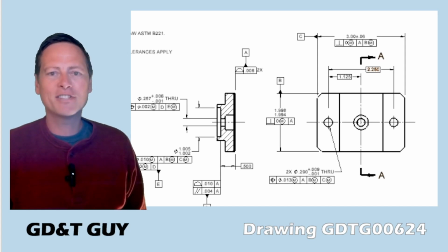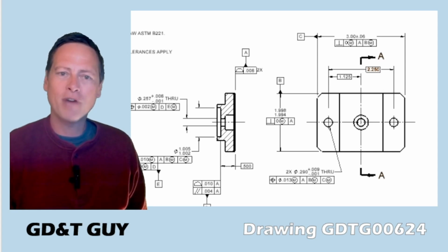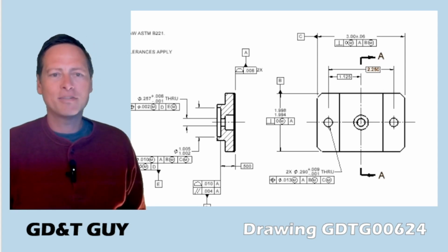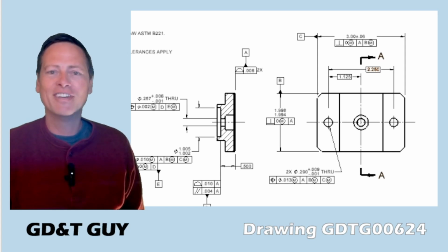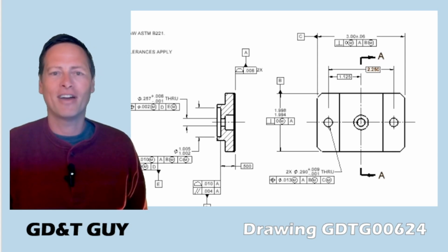I start with this one partly because I have, especially in the past, made a lot of drawings of rectangular parts with this approach to the datum references. And also, probably like many of you, I subscribe to the view that circle M is most likely to be correct when we reference datum features of size, unless there's a good reason to go to a different material modifier, and we'll see if there's a good reason, okay?